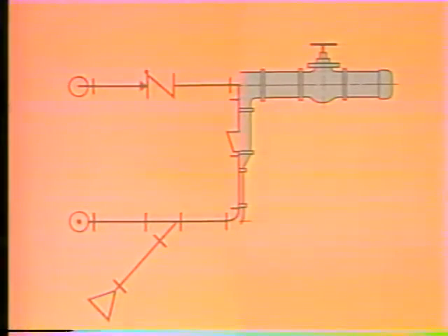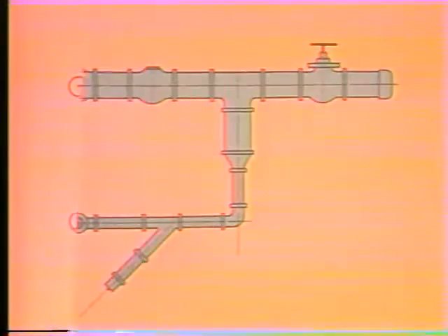A piping system can be represented in one of two common methods, the double-line print and the single-line print. A double-line print is a pictorial representation. That is, it uses pictures of the piping and components in the system. It is easier to follow than a symbolic representation. The major disadvantage of a pictorial print is that it takes up a lot of space. A large or complex system cannot be easily drawn on one page or sheet of paper.